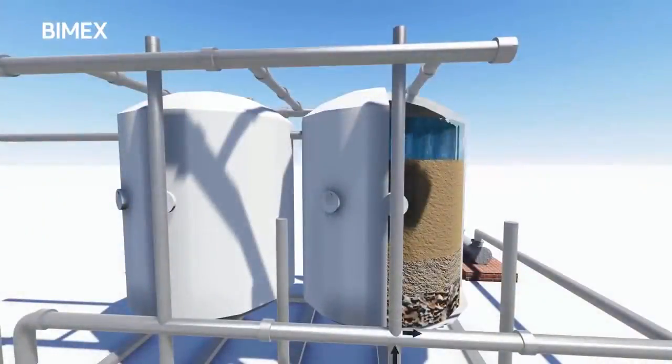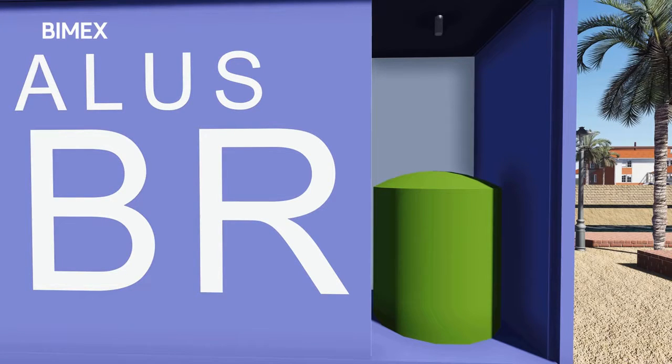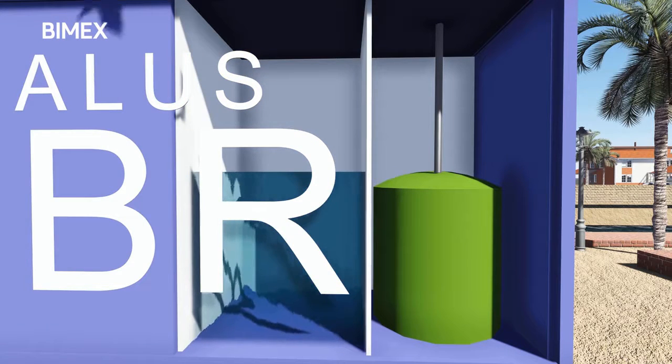Then the water flows into tertiary filtration through a sand filter to remove any remaining solids. The water then flows through an activated carbon filter to remove any odors from the fluid. Then the fluid enters the chlorine contact tank for disinfection.